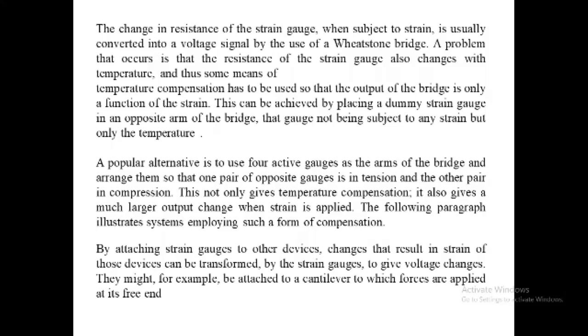The gauge is glued onto the device by an adhesive. When an object shows physical deformation, its electrical resistance changes, and that change is then measured by the gauge.